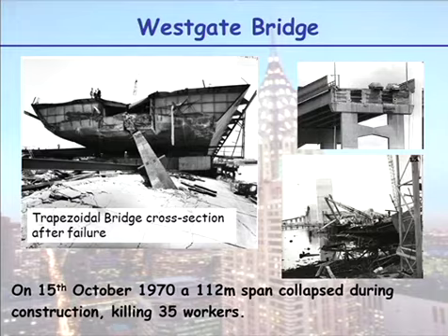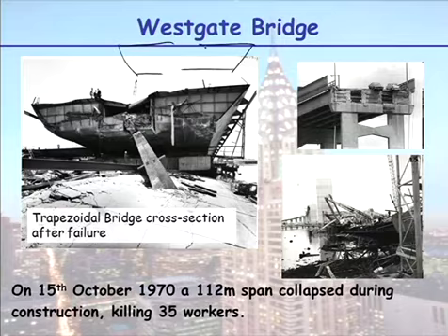But there was all this extra weight on the actual structure, and they hadn't connected it all out. So they started connecting it up, but with this extra weight on, they found that bits of this plate here started buckling. Each of these sides of this bridge, there were 2 sides, and there's a plate in here and some nuts that joined it all up, and they found that these bits of plates were starting to buckle.